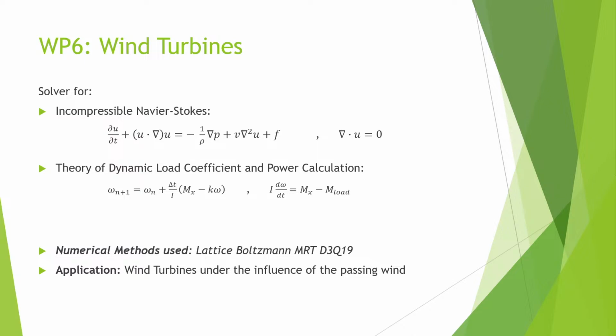And the software calculates with STL, finds the intersecting points, applies an innovative second order no-slip boundary condition on these structures, moving and non-moving, and rotates the parts at every time step, recognizing transitioning of fluid to solid nodes and solid to fluid nodes, and also identifying the cross edges that cross the STL elements automatically, and calculates forces, moment of inertia, center of gravity, center of origin, torque as well, and rotates the whole structures or keeps them stationary if they are stationary.